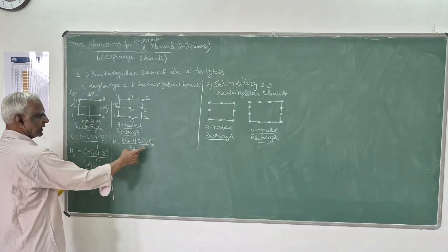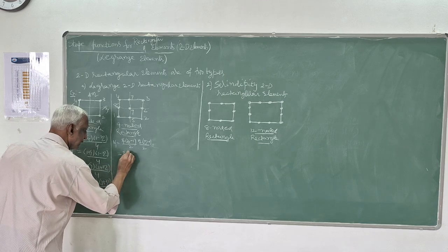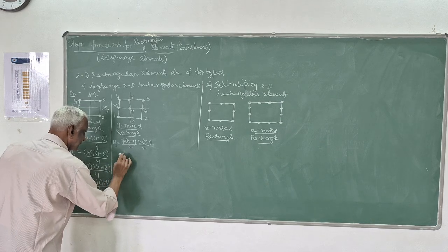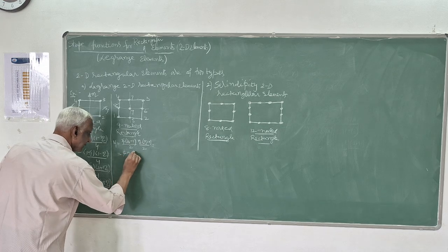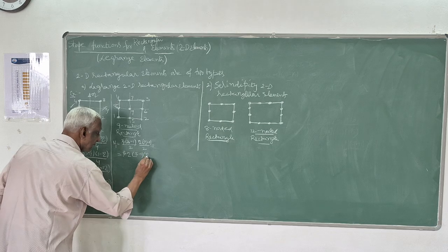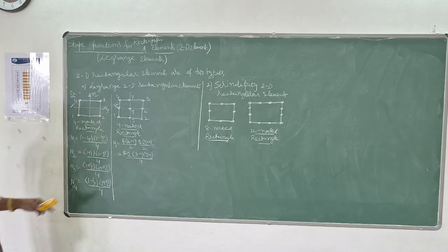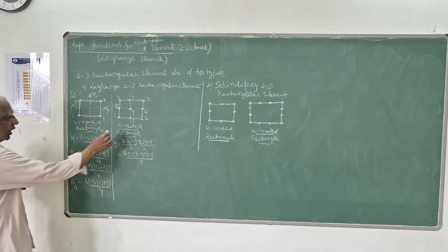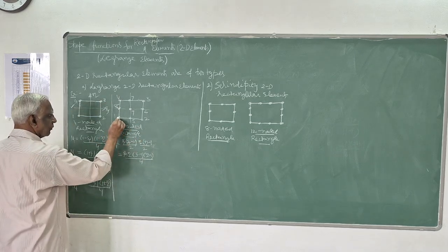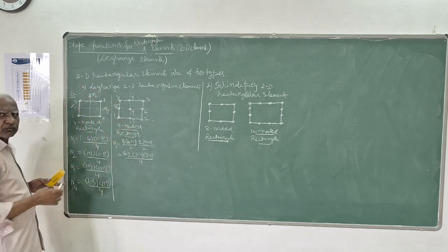The shape function N1 is psi eta into (psi minus 1) into (eta minus 1) divided by 4. That is your N1. Node 1 is common for element 1, 2 as well as 1, 4.